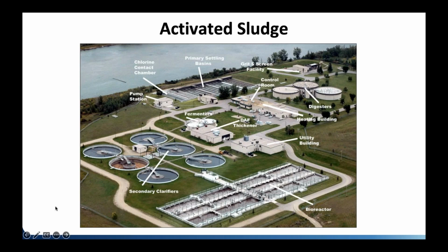After it flows through the bioreactor, it goes into these clarifiers, called secondary clarifiers, and solids settle down. Then they take some of those solids and put them back into the aeration basin. Why do they do that? Because those solids have bugs in them. The water looks all nasty, but really it's being broken down and cleaned. The bugs settle out and get sent back, so they're hyper-concentrating the amount of bugs in these bioreactors to get the most efficient treatment possible. It's all about getting the bugs, the oxygen, and the food together.